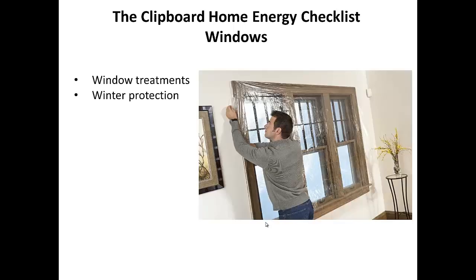In the winter protection, where a lot of homes don't have a good window system, or double glazing, with the newer windows, you can put up once a year and take down once a year a product by 3M that is kind of like a shrink wrap, cellophane, saran wrap, if you will, that's made for windows. And so this will give you that extra glazing and help reduce air infiltration that comes through old windows in the wintertime.